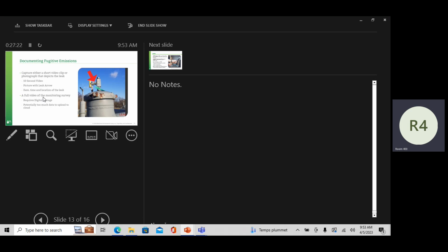So they'll record that, and then at the end of their survey, they go back and capture the 10-second videos at the end. It's easy. These facilities aren't that big, and you know where your leaks were. So you go back, you capture this data, and that's what we share with our clients, that 10-second leaking video, so that maintenance personnel can review it and go, okay, I know where the leak is. I know what I need to do to get prepared. I need this gasket, this wrench, whatever that might be. So they're prepared whenever they go out.